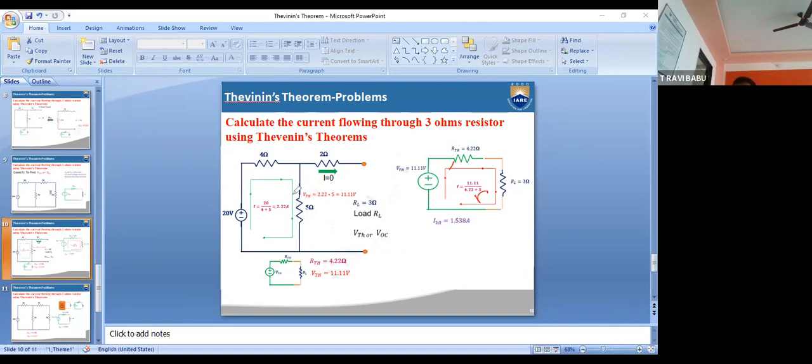So I want the voltage across this resistor. What is the formula for Ohm's law? V equal to IR. We know the R value, 5 ohms. We require the current value here. It is a single loop connection. So how can you calculate the current here? Two resistors, total resistance. What is the I formula? I equal to V by R.